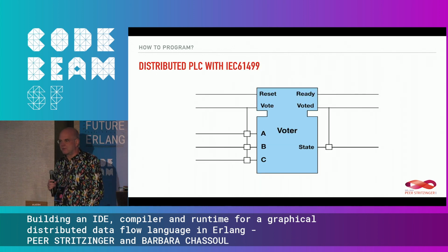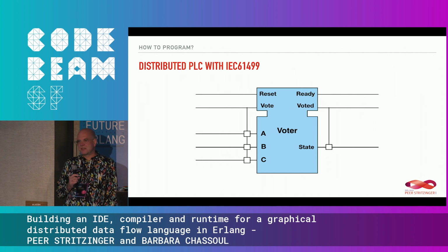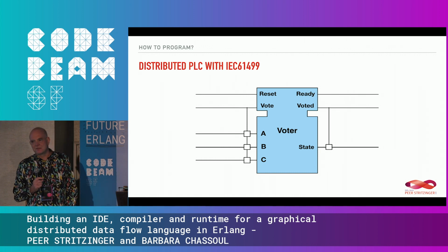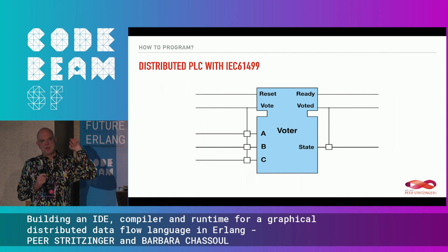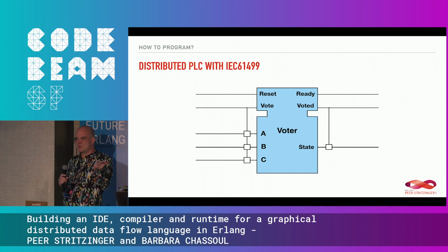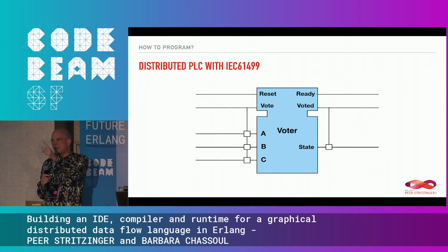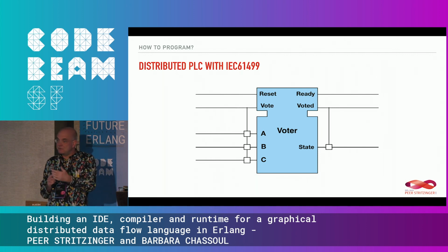But now to the future, which means 20 years ago. There was the idea that it would be cool to do distributed programming with PLCs, which you could do ad hoc by hooking them up to a field bus, and it runs in cycles, and you cyclically send data over the field bus, which then results in interesting effects when the cycle times change. So it's a tar pit of race conditions, the whole thing. You add an unrelated line of code to one of the PLCs, the cycle time changes, and suddenly your process doesn't work anymore. So that's not good. Of course, you can make your own handshakes with the synchronous thing, and you need to, but that's tedious.